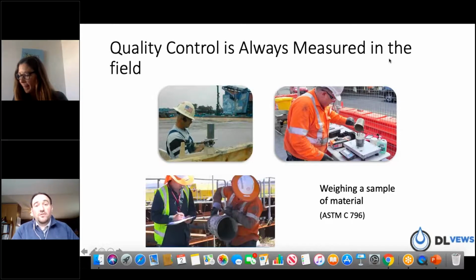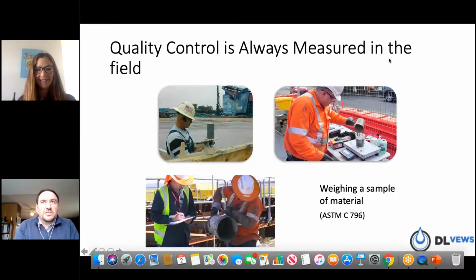If I've learned anything, Cassie, in my time with cellular concrete, it's checking your checks and balances. Sometimes if it's a really delicate project and you really need to hit the density on the head, even just checking the neat slurry coming off the ready-mix truck before you foam it can be a critical measure in making sure you get the right product. So it's like anything. As long as you weigh it and check it and it's right where you think it's going to be, the weights will give you your finished compressive strength at the end of 28 days.